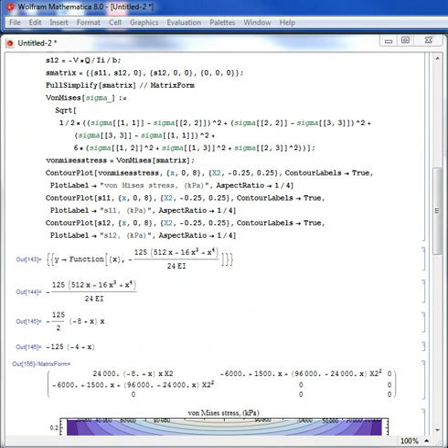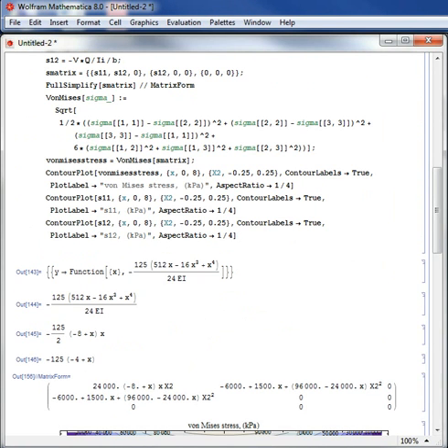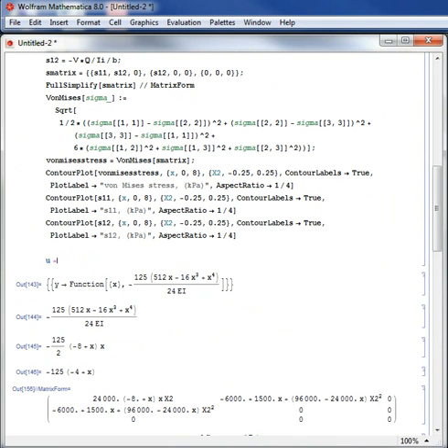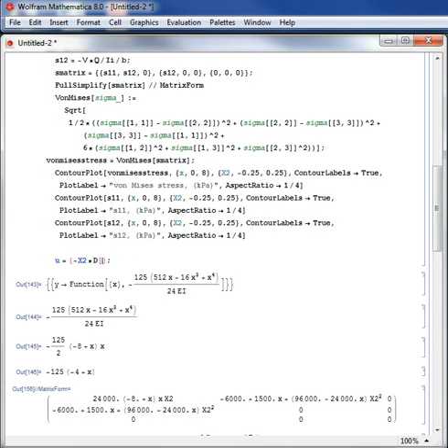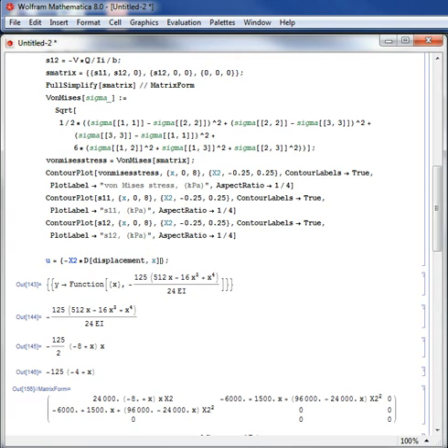We would like to also plot the displacement of the beam. Basically the arrows show how the beam is displacing. So I'm going to take the displacement vector. I need a horizontal displacement and a vertical displacement. The horizontal displacement in beams is given by negative x2 multiplied by dy by dx, and the y, I'm storing it in a variable called displacement. The vertical displacement is y.